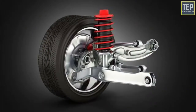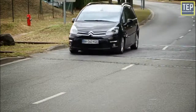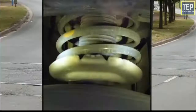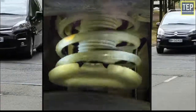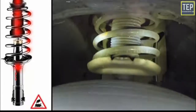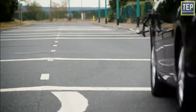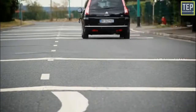Now let's find out how these components work, starting with the springs. Springs act as reservoirs of energy. When the vehicle passes over irregularities of the road, it compresses the spring. This energy is released when the spring expands subsequently, and with the help of dampers, the energy is converted into heat, and the spring absorbs the shock and avoids transfer to the vehicle frame.